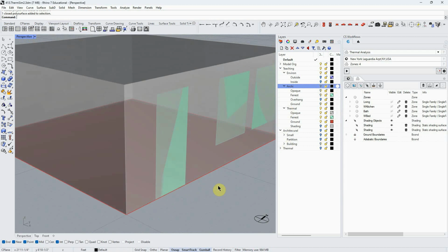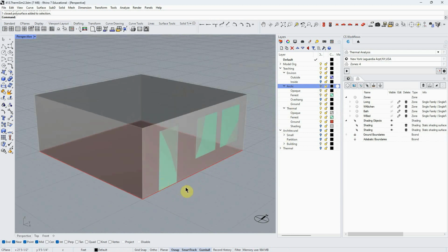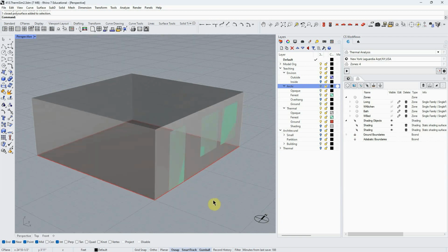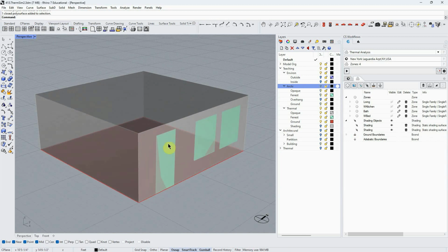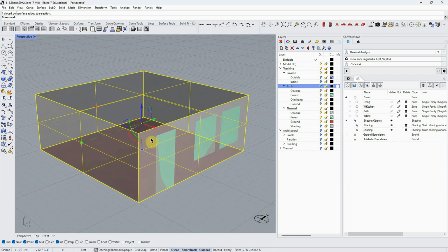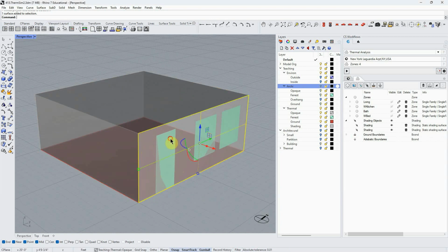So that's the first thing that's really important. We're only talking about one point thick surface that goes around the entire volume of air that's our zone or our building. And why is that important? Well, if I don't think that way and don't model these windows in the exact same plane, this and this have to be in exactly the same plane, then I will get errors.